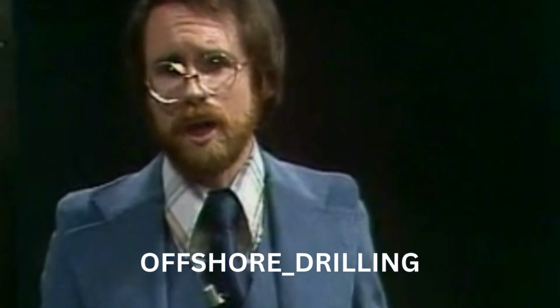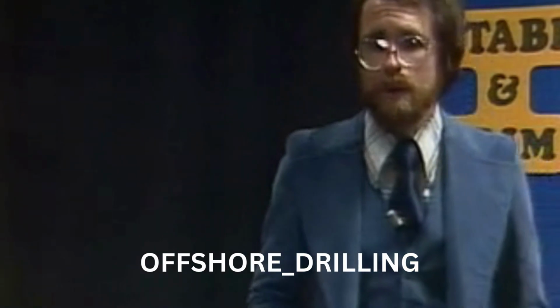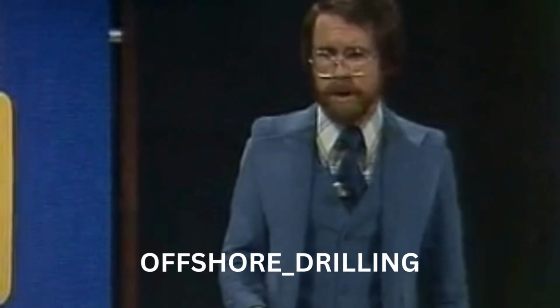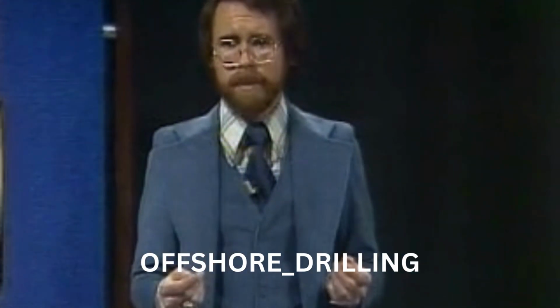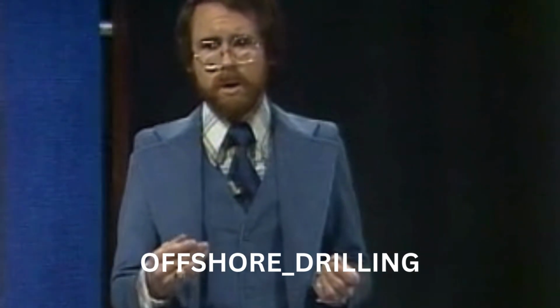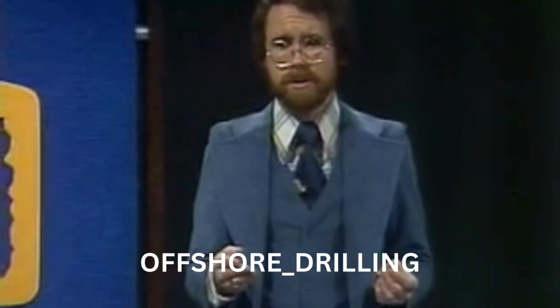Our goal is to have an easy rolling period on a ship. Let me point out here that we are talking about a ship and not a semi-submersible. On a semi-submersible, we want a tender or cranky vessel so that the roll is very slow and manageable to avoid problems with the drill string. We'll talk more about this later, but for right now we will be limiting our discussions to ships.